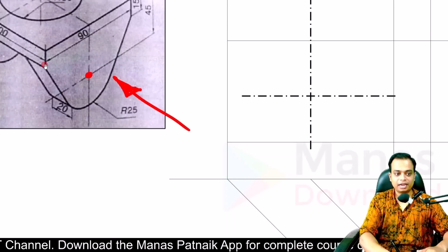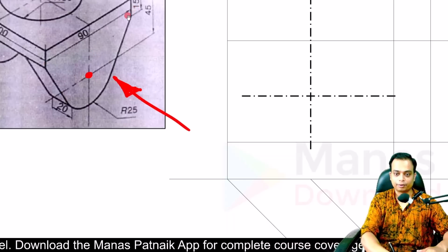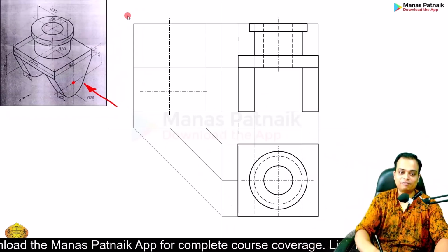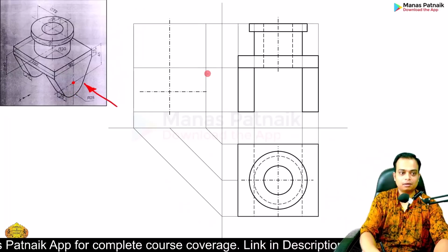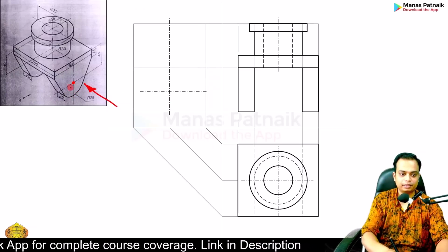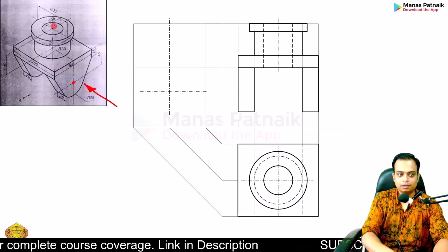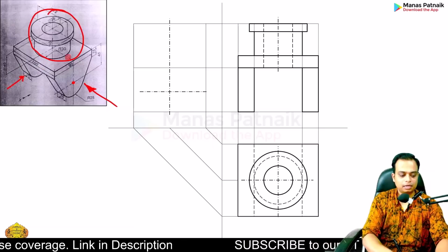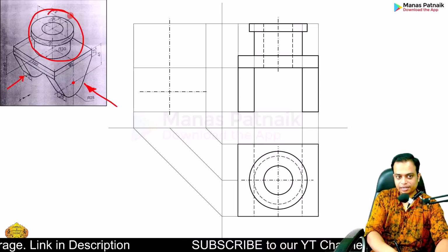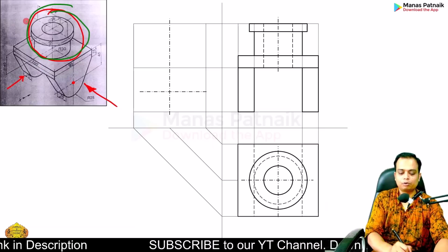This circle will have tangents through these 2 points. Okay, and we are going to do it in that fashion. So the radius is 25. Can you make this? Just a second. We are going to make that circular profile later. This from the front, and when you take a look at this from the right hand side, you are going to see the same profile.